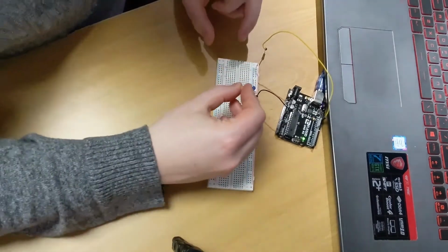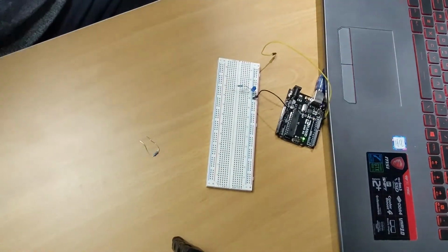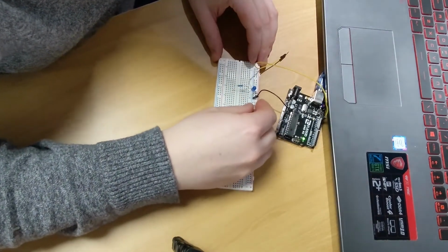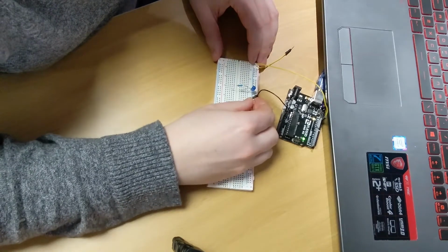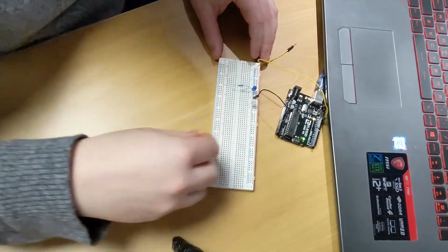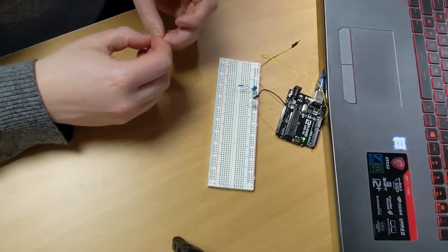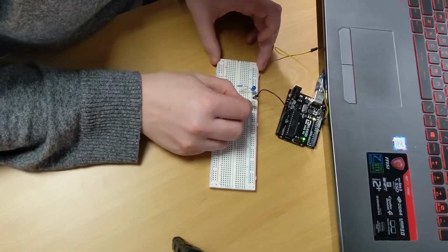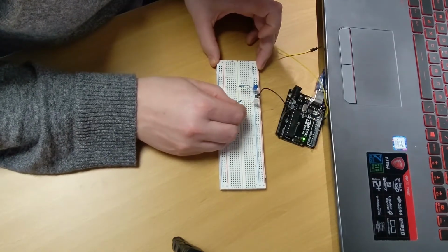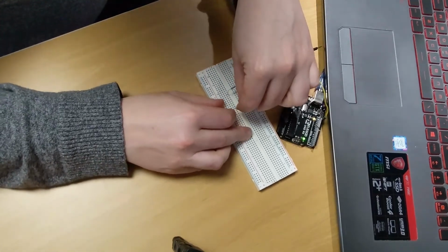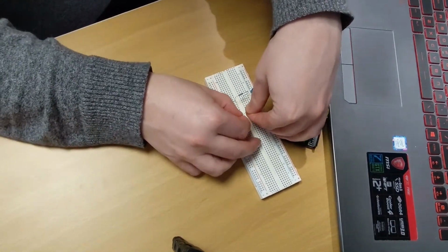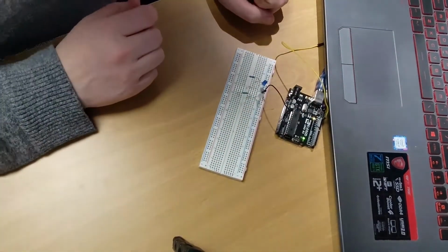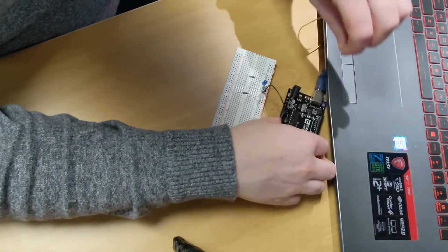So I'm going to put in another LED. So again, I'm going to hold it up to the light, find the big flag, which is negative. I'm going to go into the negative here. Okay, same again. I'm going to put another resistor in. Again, I'm using the same row. If you remember, it's got to be in the same row because they're connected. And then by having two ends of the resistor in each side, I'm connecting those up. So I'm just going to have to push this one in a little bit harder to make sure it's connected. There we go. Now I'm going to have to think, how am I going to connect this up to my pin?